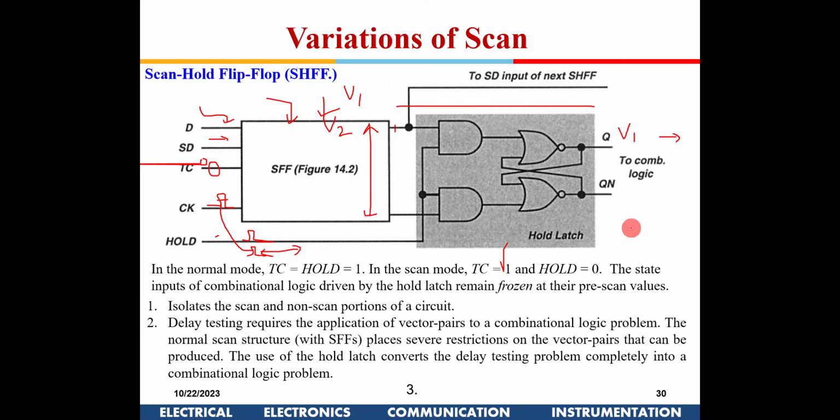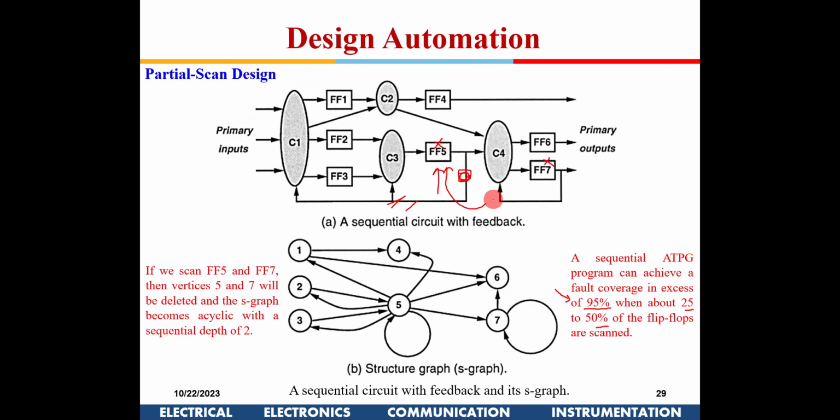But in the design, if we could incorporate within the chip something which can generate a test pattern, and not necessarily for a particular block, right? Suppose this is one block. Not necessarily do I test this block independently, and this block independently, and take out the result and compare with a lookup table. Give one test vector here, then the second test vector here, compare the result, third test vector, compare the result. All those things will be time consuming.